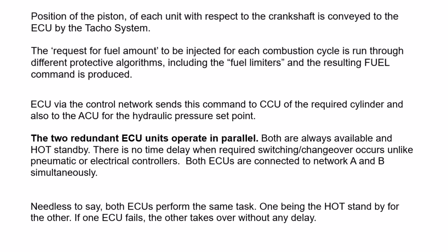The two redundant ECU units operate in parallel. Both are always available and in hot standby. There is no time delay when switching or changeover is required. Unlike pneumatic or electrical control, both ECUs are connected to networks A and B always. Needless to say, both ECUs perform the same task, one being the hot standby for the other. If one ECU fails, the other takes over without delay.